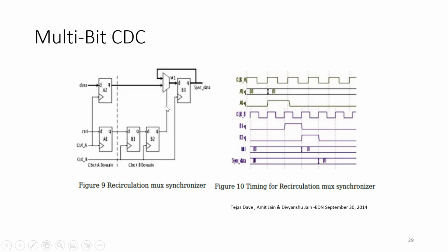If I have high, I will take this as my input and send it out. If I have low here, I will take the input 0. What is the input 0? My input 0 is the output Q. So it would remain in the same state, no change, unless I have high here, I will get new data. So I will get new data when here is high.